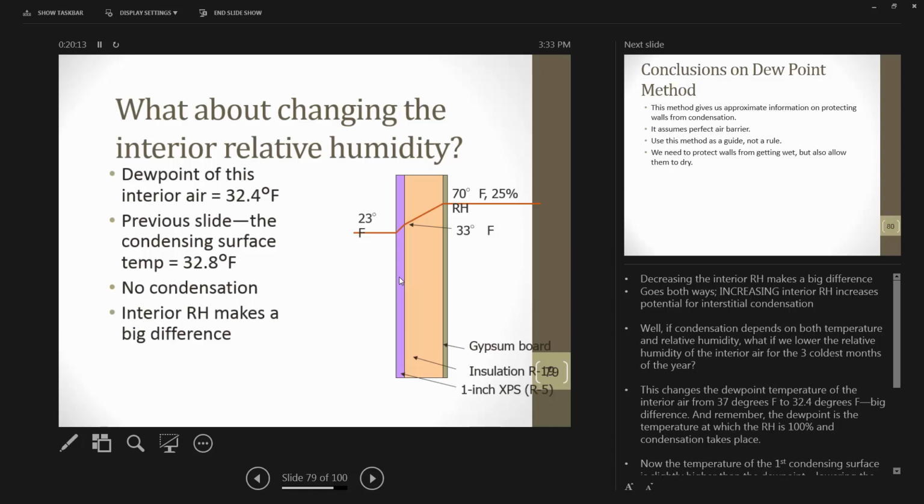What makes this 33 degrees Fahrenheit is that we're getting conductive and convective heat going towards the outside of that wall. If we add insulation in here, we increase the envelope on the inside, and we're actually going to get less heat directed towards that exterior condensing surface. So all of a sudden, instead of this being 33 degrees, that temperature is going to drop significantly. Make sense? I'll bring a slide next time and show you that. I thought I threw it in there, but I didn't.